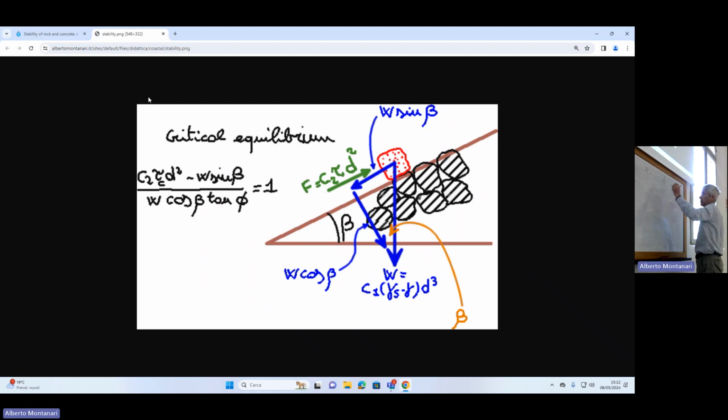And then it depends on the friction, called tau here. The hydrodynamic forcing induces a friction over the smooth bed, and the friction generates a tangential tension. The tension is a force per unit area. Multiplied by the square of a length, you indeed get a forcing, okay? The tangential friction depends on the velocity of the flow, of course, and also on the type of flow and of fluid. So the friction depends on velocity squared, as you may remember, because I'm sure that you have already studied hydrodynamic forcing.